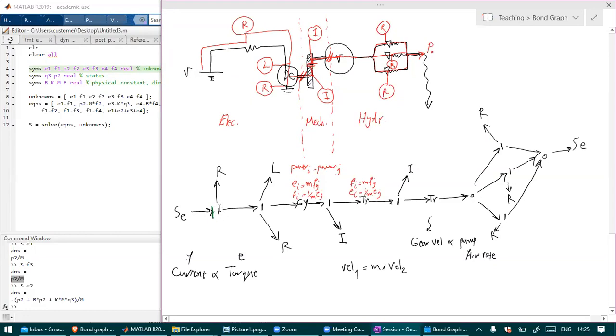And the one junction, we know that it defines the flow of all of the ports except one, but this port that we have the causality for is not defining the flow here, so we cannot proceed at all. Okay, either we can start from the other end or start from an element with known causality. The inductance, it's like a mass. It integrates the effort, so it defines the flow. So the causality is on this side.